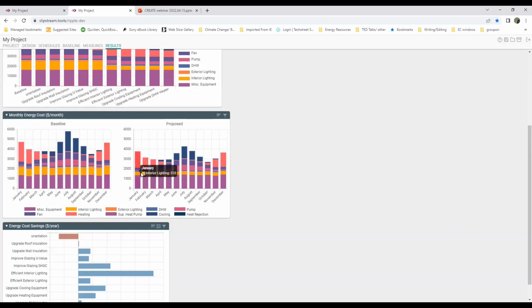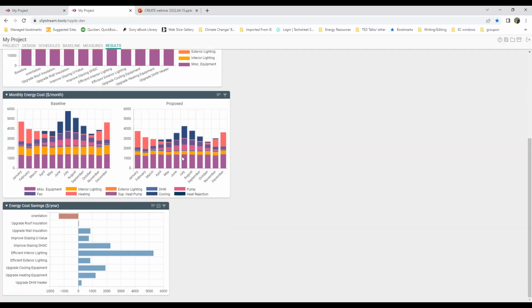So you see that reflected in the yellow bars here. The yellow bars are much smaller in magnitude in our design condition versus in the baseline case. And this is also an opportunity, if we did just the lighting, to talk about energy interactions, like Jenny pointed out. What we would see is that the lights also emit a bunch of heat into the space.